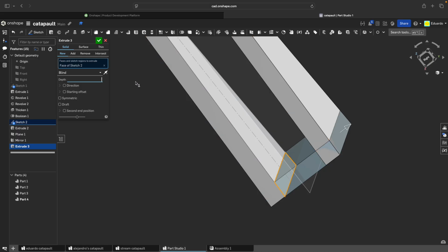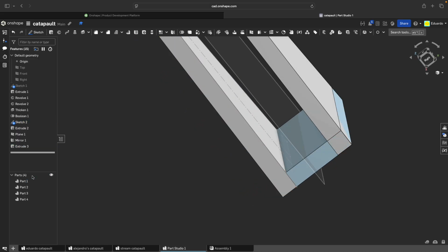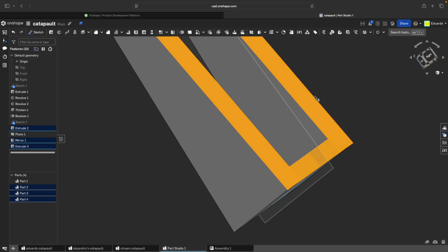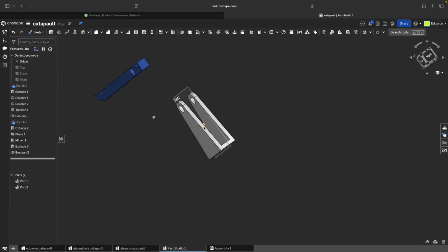I'm back. Okay, so make sure it's new, all connected. So see how we have these different parts. So we're just going to highlight them all. Don't grab it actually. Hide the sketch. Grab all the shapes. And now press Boolean. Check it off to save.